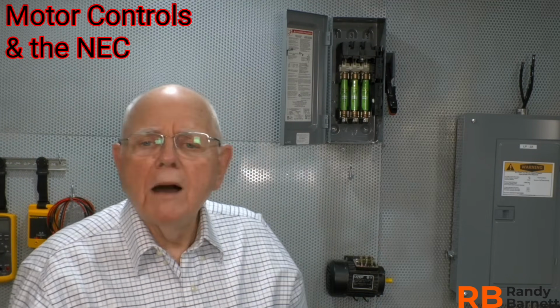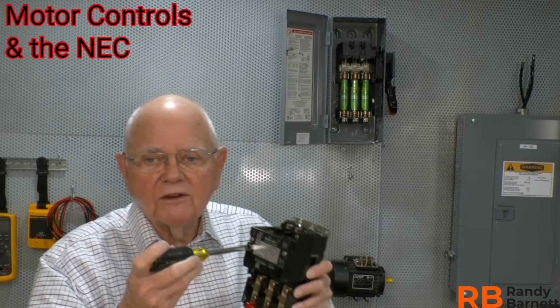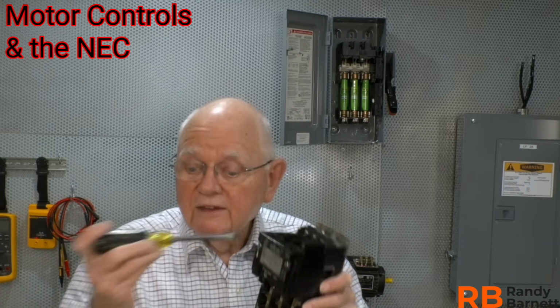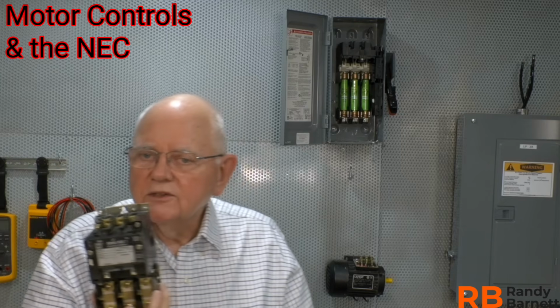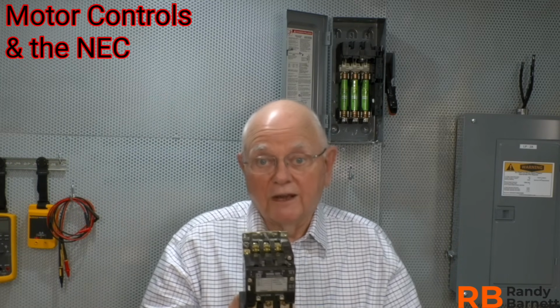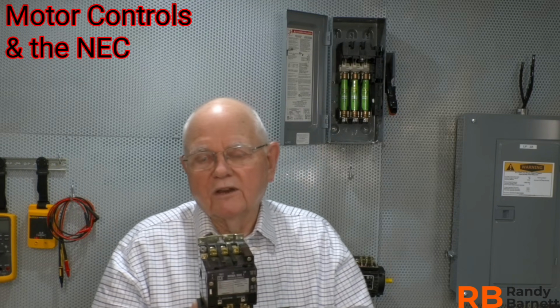I can bump the motor starter, a term you might hear. I can take my screwdriver and push on a little bar on the side of this, and maybe you can hear that, but I'm opening and closing the contacts. Not a good thing to do for two reasons. One is when I do that, I'm standing right in front of it. So if something does go wrong, it's right there in front of me.